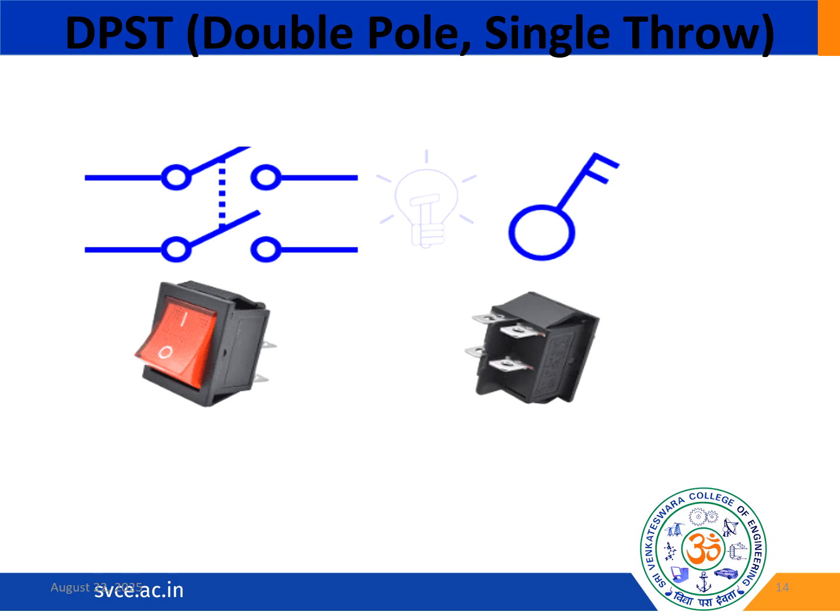This switch has four terminal pins. Two are kept for input and the other two are for output. DPST switches are used to control a single circuit. Normally we use DPST to control a single circuit while both the contacts need to be actuated. For example, a DPST switch is used to break both the line and the neutral wire for the on and off operation of the connected device.